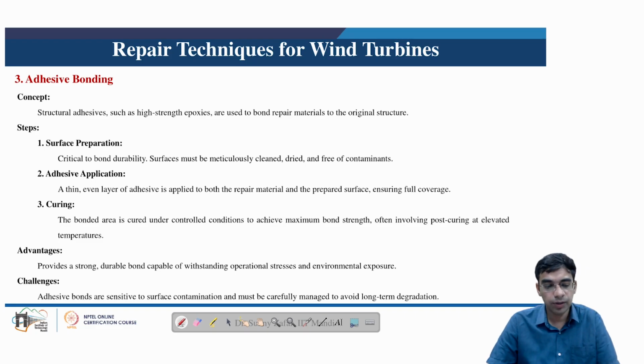Curing involves the bonded area being cured under controlled conditions to achieve maximum bond strength, often involving post-curing at elevated temperatures. The advantages of adhesive bonding involve a strong, durable bond capable of withstanding operational stresses and environmental exposure. Challenges of adhesive bonding involve adhesives being sensitive to contamination, and they must be carefully managed for long-term degradation.